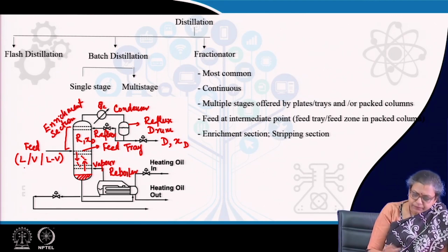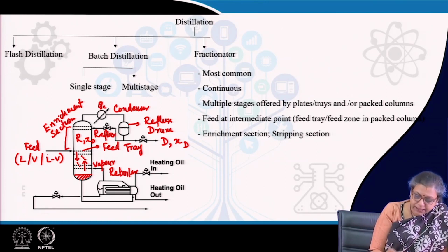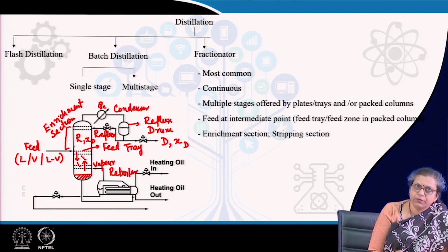And what will be the purity that we will get from the feed composition and the flow rate with which we started? We can achieve that by deciding upon the number of stages in the column. So, depending upon the purity, we decide the number of stages. Initial calculations assume that on each tray the vapor and liquid leaving are in equilibrium. That means we perform the calculations assuming ideal contacting trays, knowing fully well that ideal or equilibrium trays do not exist.